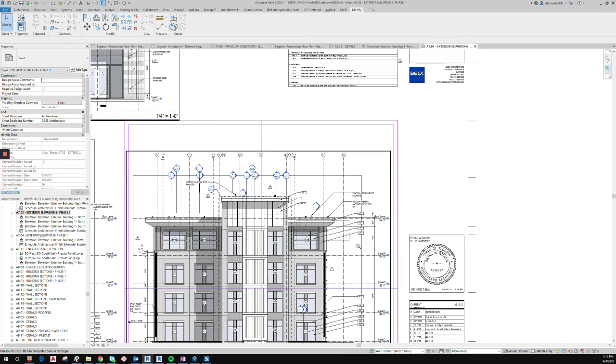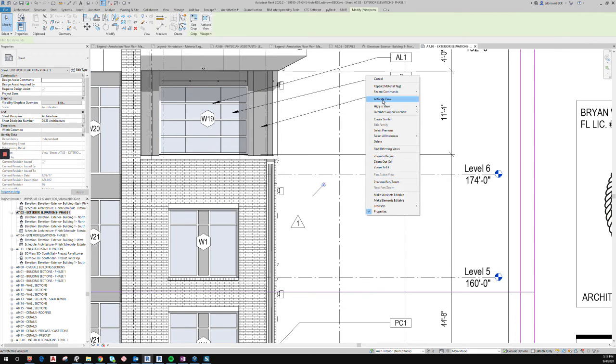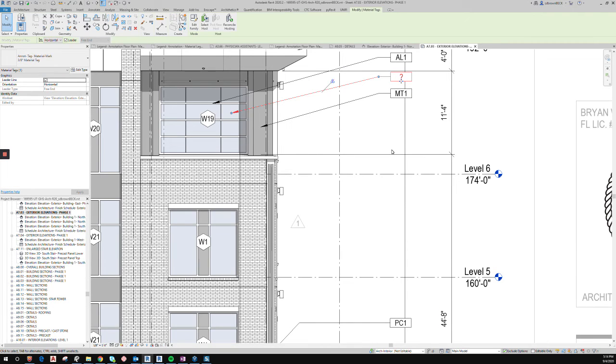But you can see here, this is a good example. So sometimes, and I'm not sure what causes this, occasionally a material will lose its mark. Typically, if you just hit the arrow key, just a quick arrow key, one direction and then the other, it'll re-find its host. That happens for various reasons, but if you see a question mark, don't freak out.